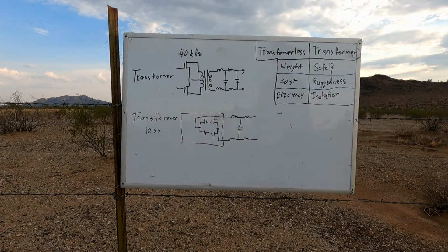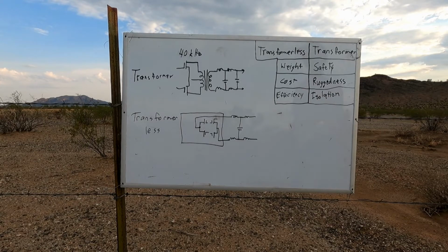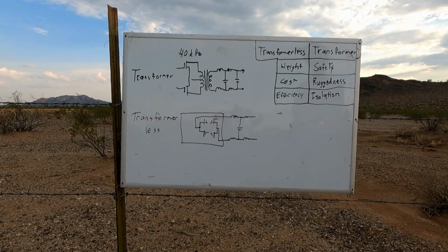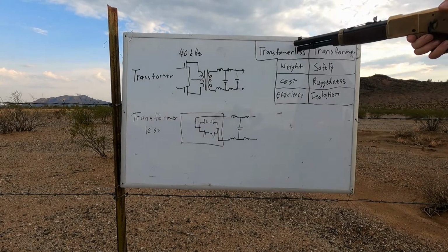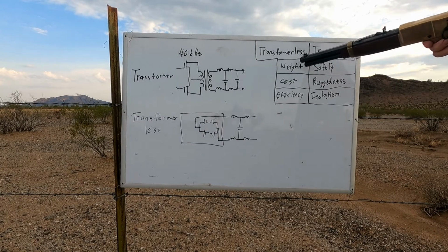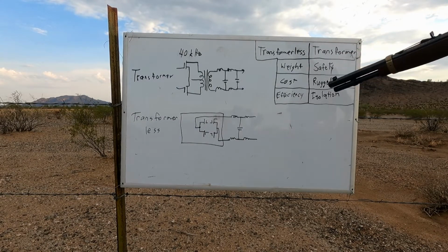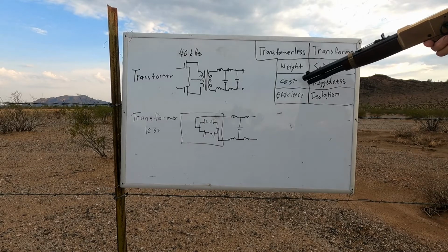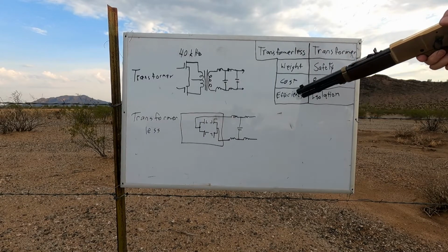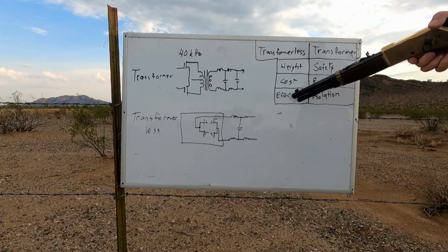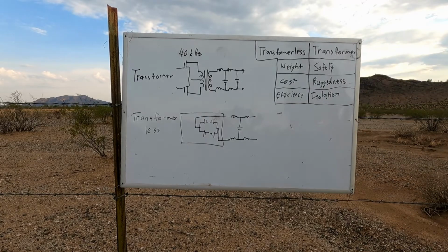Now we'll talk about the subject of transformers in inverters, because aside from high frequency, low frequency, we also have transformer versus transformerless. And transformerless inverters at first glance have advantages in terms of weight. Transformers are big, heavy things, and transformers are not exactly cheap. And you get somewhat of an incremental increase in efficiency in the transformerless inverters.